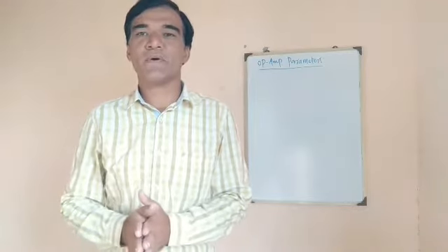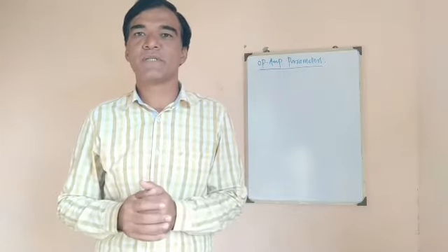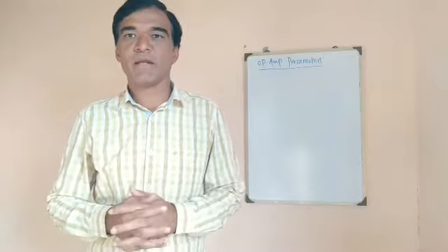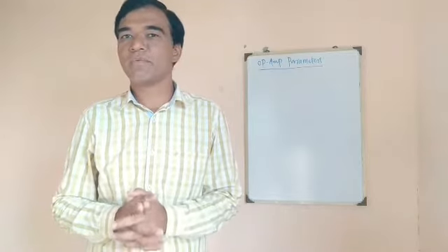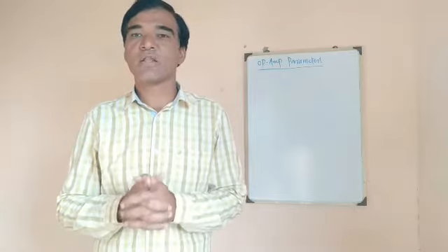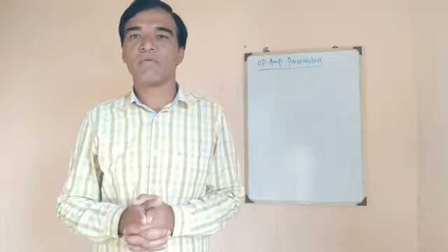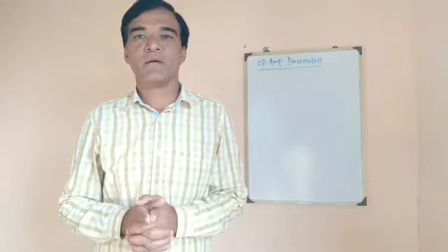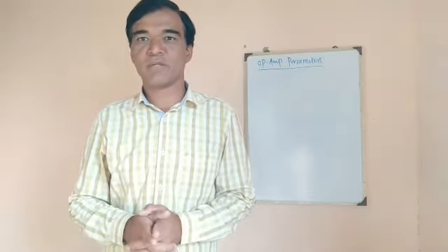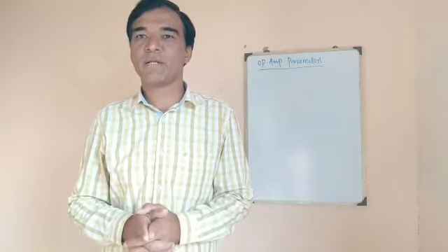In my last class, we discussed the comparator, which is one of the important applications of the operational amplifier. In a comparator, remember that we use the open loop configuration, not a closed loop. Whereas in all other applications, we have used the op-amp in closed loop configuration. Today we will discuss some important op-amp parameters.